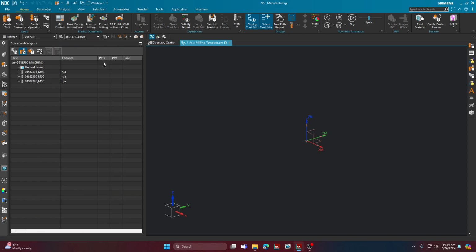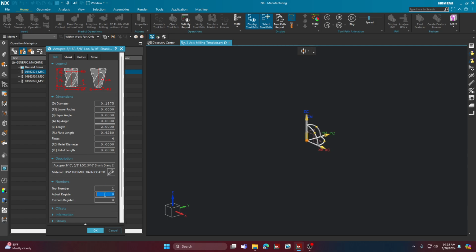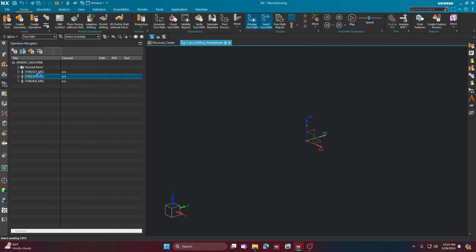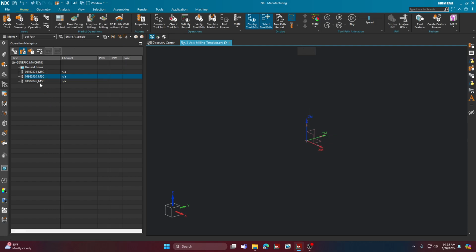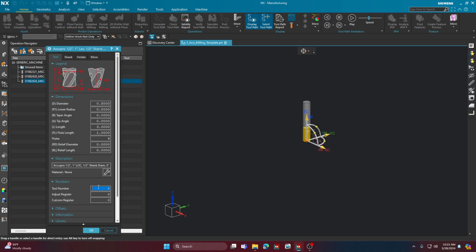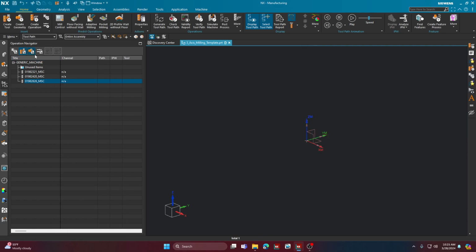And that's it. You can just go ahead now and assign the correct tool number. So I'll double click on these guys here, right? My tool number is 1, my H value is 1, and then of course you just keep going for the other tools. 2, 2, and finally 3 and 3, okay? Just like that. The next one is going to be our geometry view, okay?